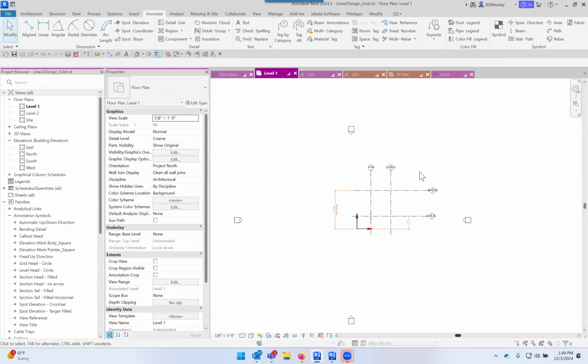Definitely not. Well, I'm not going to say definitely not. A lot of it's an interpretation thing, and I know what you're talking about. I don't use Pyrevit for that. I have ID8, but ID8 runs into the same problem, as does Shoot, the other one that I use. The problem is that when you're looking at Excel, you're looking at everything in points. You're creating a column height based off of points, a column width based off of points. The text is based off of points. So there's no direct conversion from that point to what this is, right?